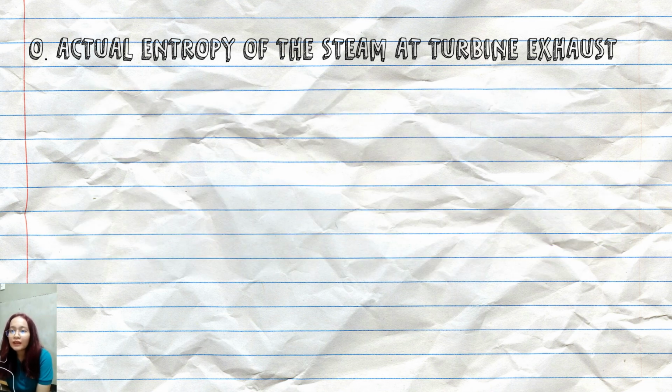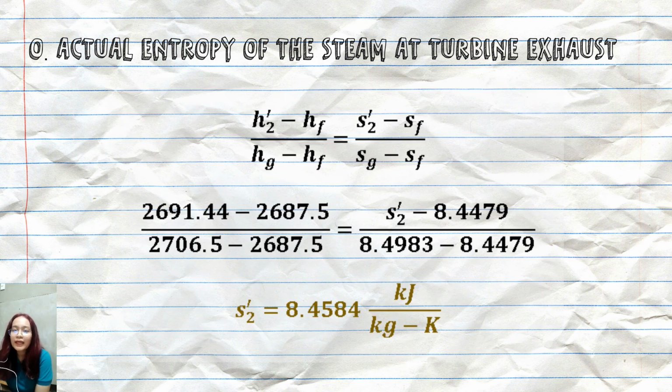The formula will be the actual enthalpy minus the specific enthalpy of the saturated liquid divided by the specific enthalpy of the saturated vapor minus the enthalpy of the saturated liquid equals the actual entropy minus the specific entropy of the saturated liquid divided by the entropy of saturated vapor minus the entropy of saturated liquid.